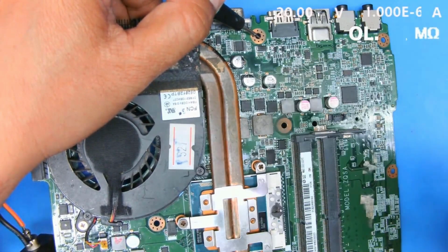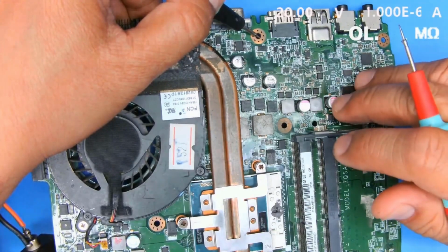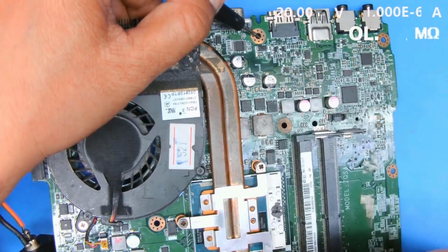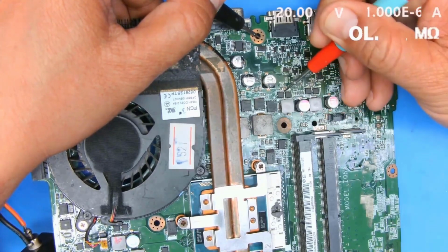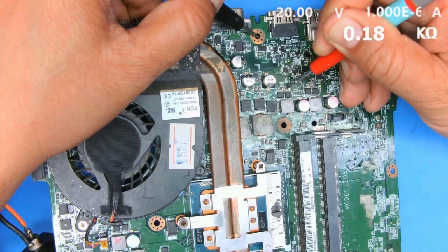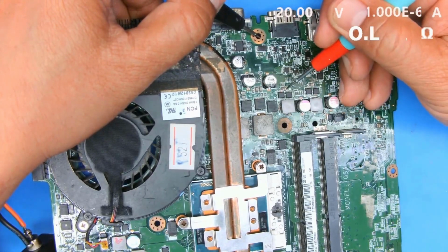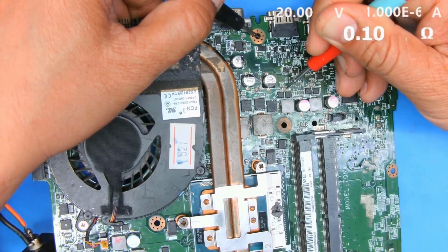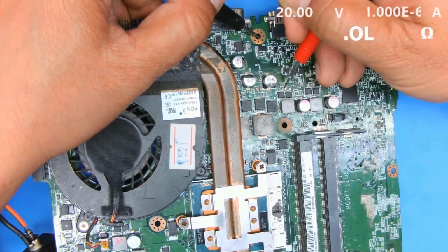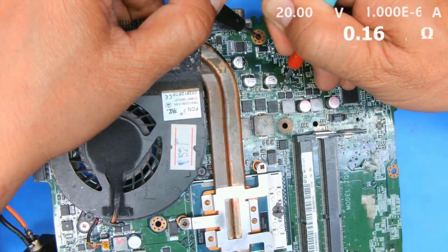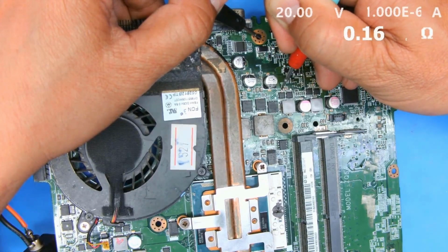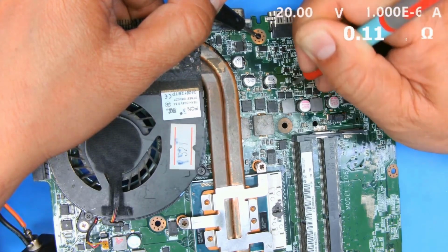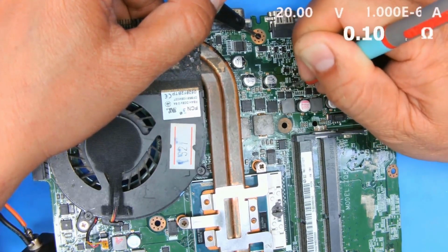But if you want to use a power supply to find the circuit information, that's possible too. For beginners, I'll teach you how to use a power supply to find the circuit information in this case. We'll immediately know it's a capacitor because it starts with 0 as well. 0.16, 0.10, like this. They're close in value, so this is a free tip. Of course, if it's a shorted capacitor, you'll see 0.10, 0.16, but you'll know that this side is the positive side, and this is the negative side, because the side with the lower ohm value is the negative side. This is how you can tell the negative side.